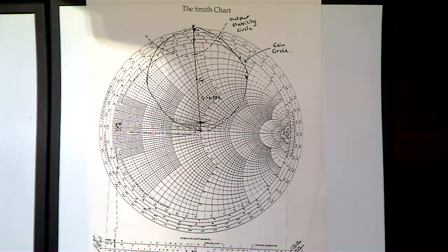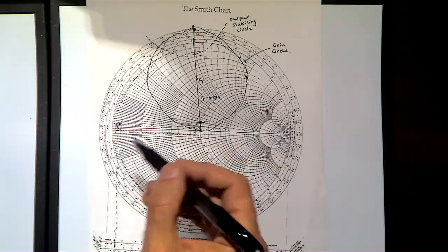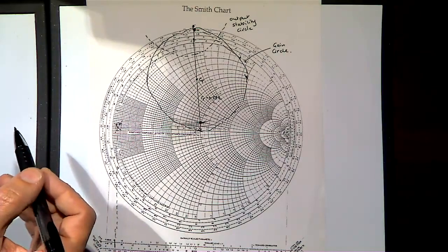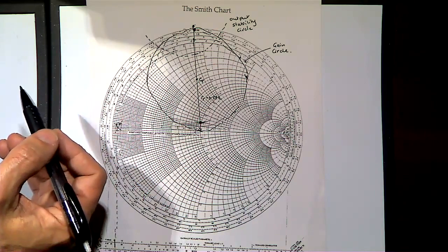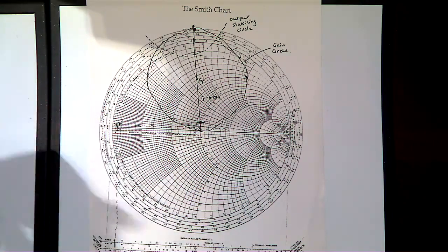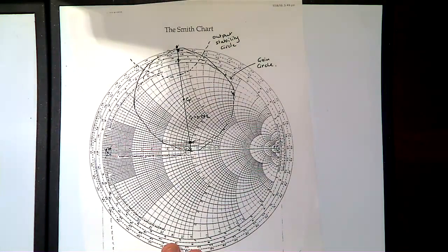That's the point. You don't really want that, because a large voltage standing wave ratio is sensitive, and a whole bunch of issues, right? So what you would do under those circumstances is choose a different point in order to get your source impedance, or choose your source reflection coefficient. You wouldn't choose it as the complex conjugate. And that's it. That's all you need to do.